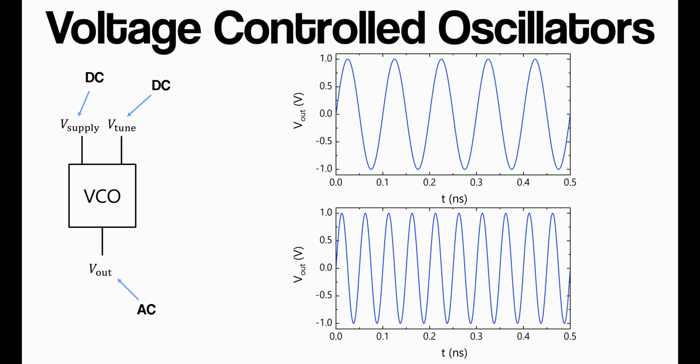So if you were to increase the voltage applied to the tuning voltage terminal, what you would see is that the frequency of the output signal would increase. And when we're actually carrying out the time resolved microwave conductivity experiment, we don't change the tuning voltage, we keep it constant. We do need to adjust the frequency of the microwaves to tune the cavity and identify the resonance conditions.